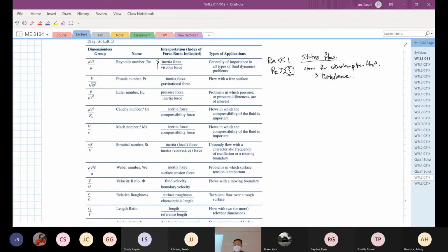Yeah, so that's what the Reynolds number indicates in the flow field. If you see a higher Reynolds number, that indicates you will see turbulent flow, which also includes flow separation, which usually occurs in the transient flow between laminar flow and turbulent flow. That's the indicator you can see under certain flow conditions. It depends on the dimensions and geometry of the flow, but still, the Reynolds number is the most important whenever you see a flow.